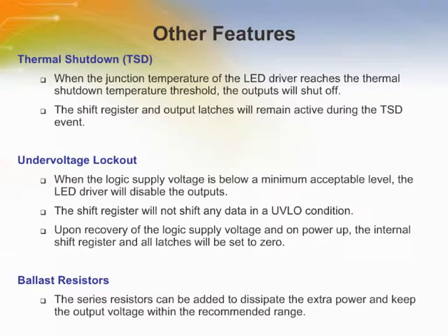The LED driver has an internal undervoltage lockout circuit to disable the driver outputs in the event of logic supply voltage dropping below a minimum acceptable level. This prevents the display of erroneous information, a necessary function for some critical applications. The shift register will not shift any data in under a low voltage lockout condition. Upon recovery of the logic supply voltage and on power up, the internal shift register and all latches will be set to 0.